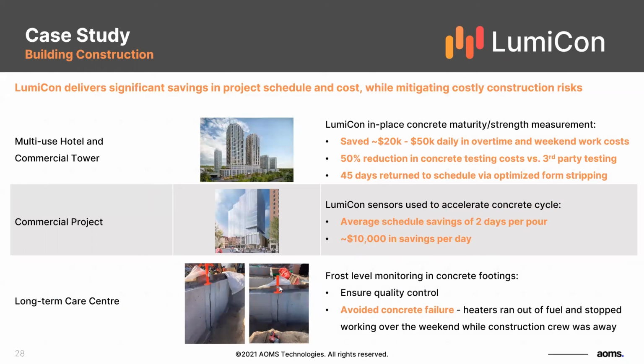And this is another example of monitoring the forming zone that I wanted to talk about here. We had the sensors close to the heater and also in the concrete footings. During the weekend, this is the value of having real-time and remote access to the data. No one was at the job site, and they got a notification from the system that the temperature had dropped. They sent someone to the job site, and they realized that one of the heaters had run out of fuel. So with this technology, we were able to prevent concrete rework.